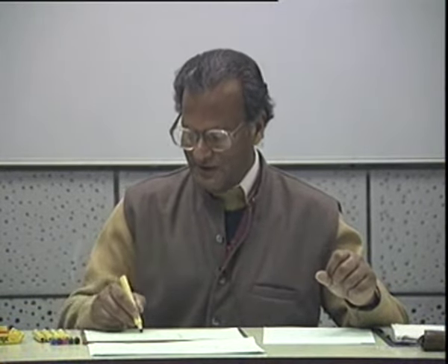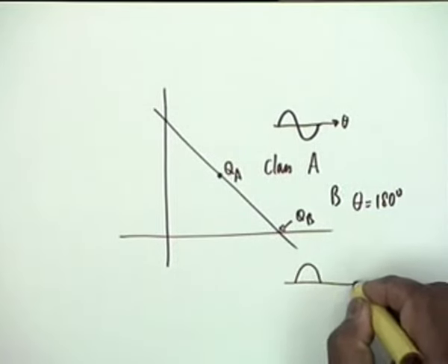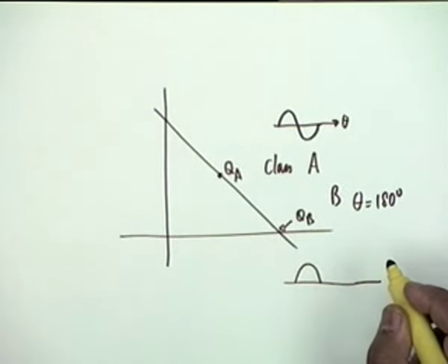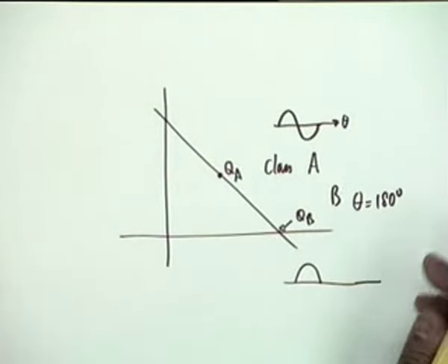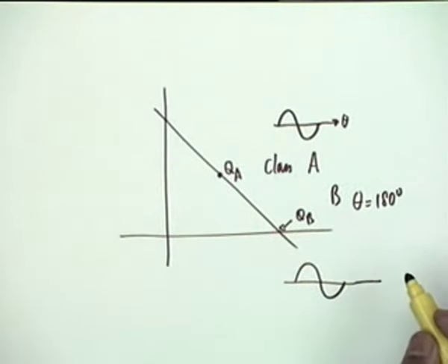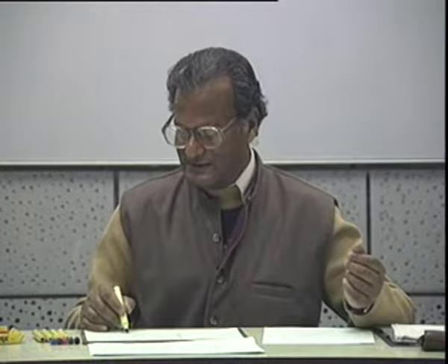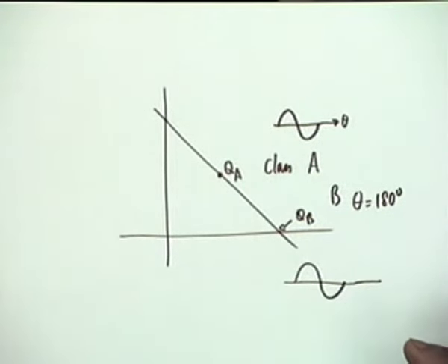Obviously, if you want the device to make distortionless power amplification, you require two devices. One will conduct during the positive half and the other will conduct during the negative half, and you shall have to combine them in some manner so that the output looks like the input. If it is simply one cycle, then obviously it's a half-wave rectifier rather than an amplifier.